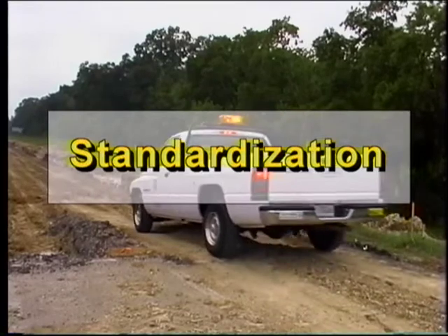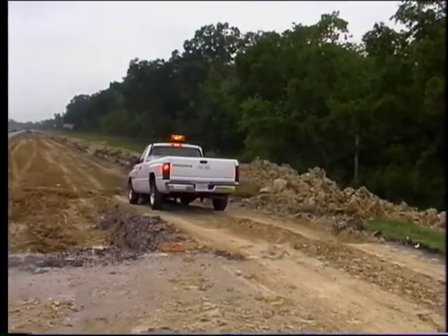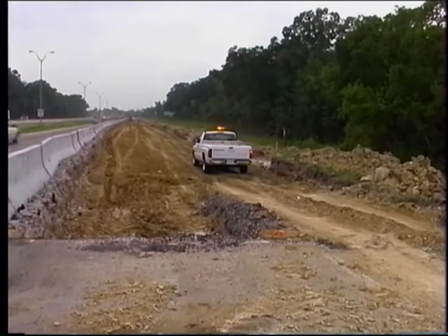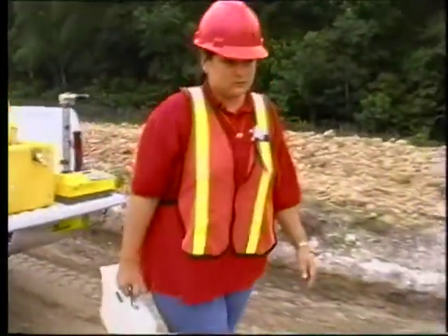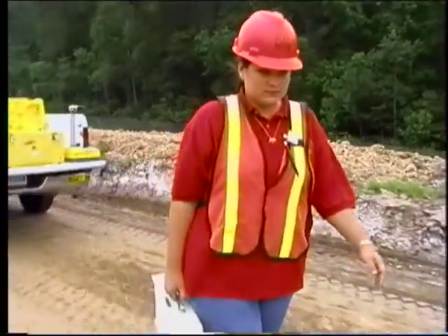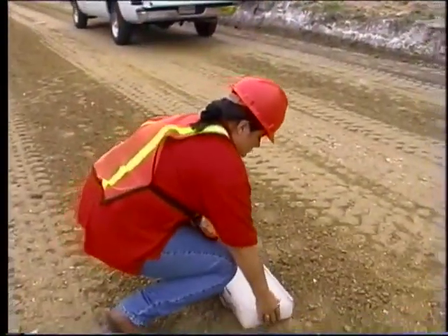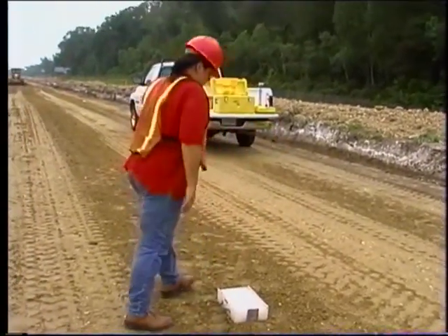Standardization. Once you arrive at the test site, the first thing you will do is take a standard count. A standard count is basically a calibration procedure used to ensure that the machine is working properly and the test results you acquire are valid. This count is compared with actual field results in order to cancel any drift or error in the equipment. Standard counts are done for moisture and density.